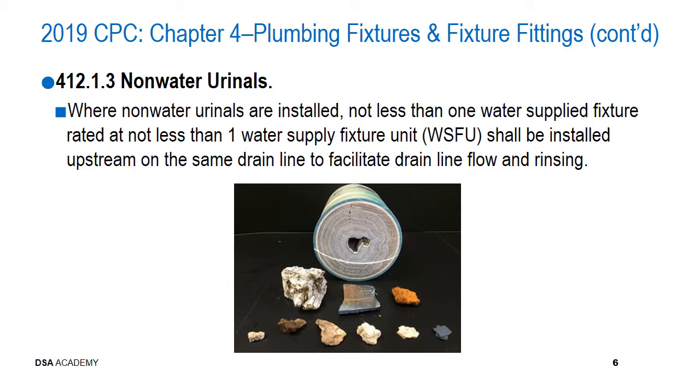Problems were identified just shortly after the installation of these particular units, primarily from a hygiene standpoint. However, and when I say hygiene, I mean sometimes there was an odor that was detectable with non-water urinals. After several years now of seeing these in use, another deficiency has been identified, and that is the fact that these particular drain outlets from non-water urinals tended to create sediment in a higher concentration than in piping where water is generally flushed through the piping.